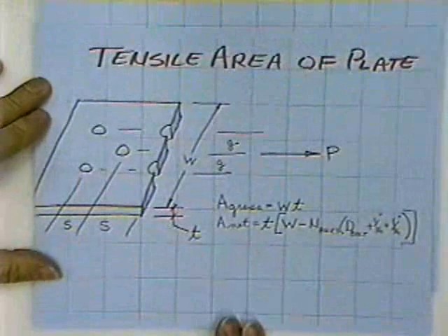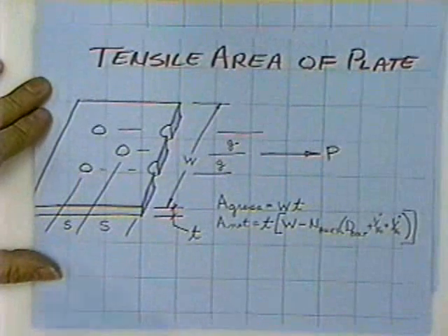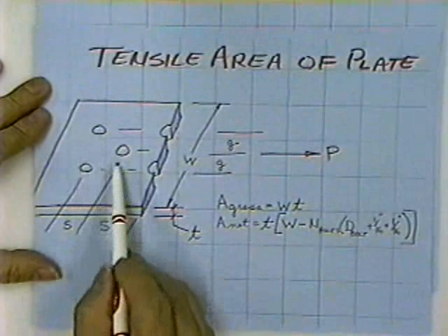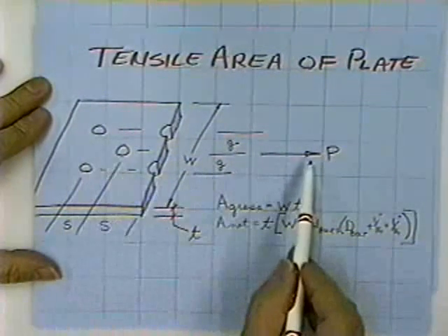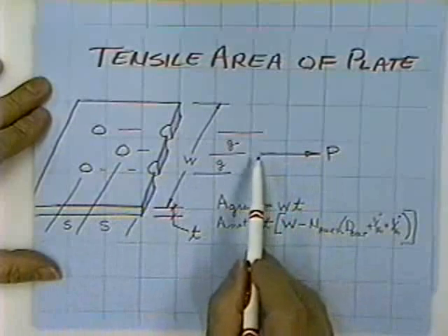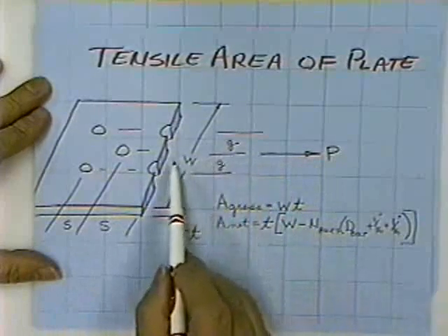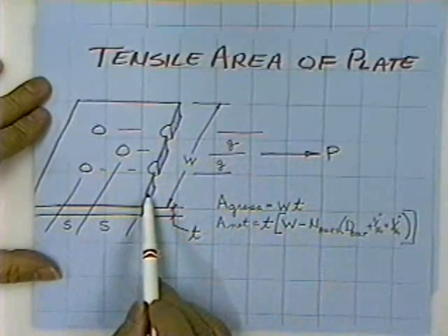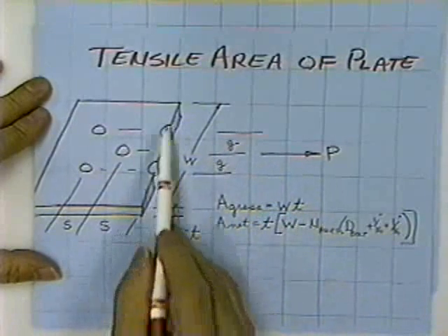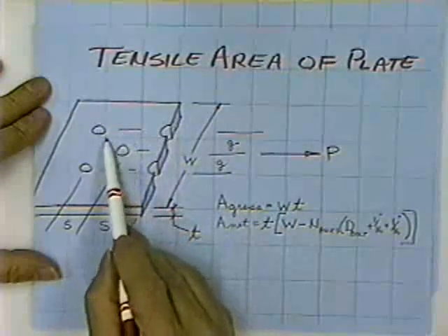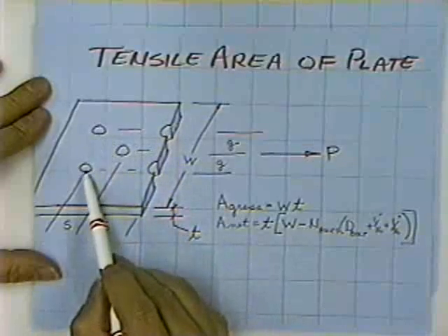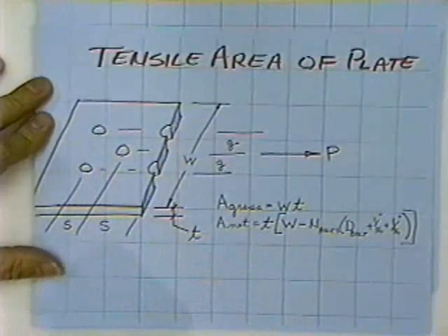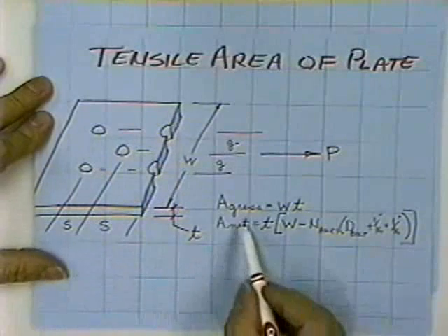The equations are straightforward and simple. There's not much to them. Like I say, we'll include them in a supplemental package. But if you have a plate that's got some holes drilled in it, as the load starts coming down the structure, it's going to hit the first weak spot and break across these holes. It's not going to break through 5 holes. There's just too much steel involved. He's got no desire except to tear across the shortest, quickest, easiest way across the plate. So he tears across 2 holes.